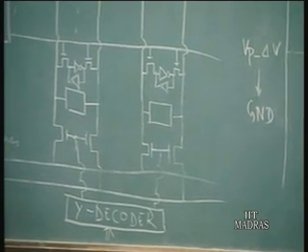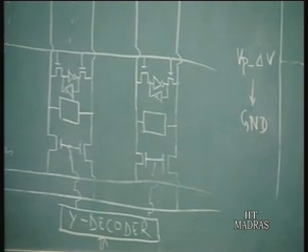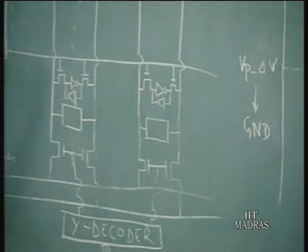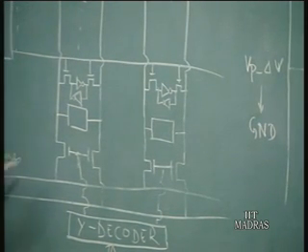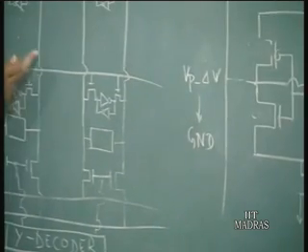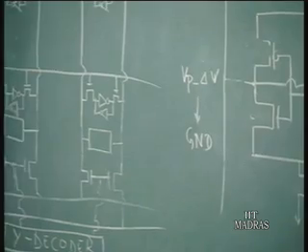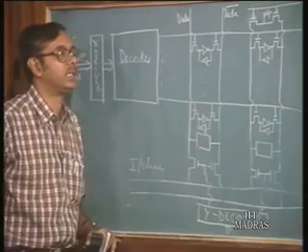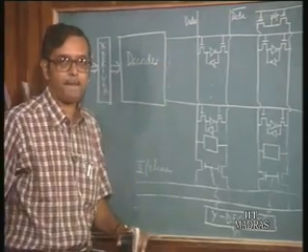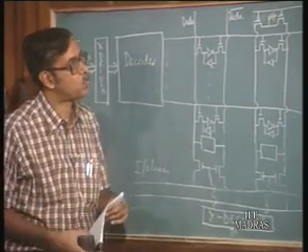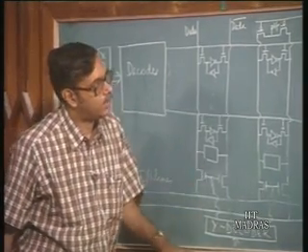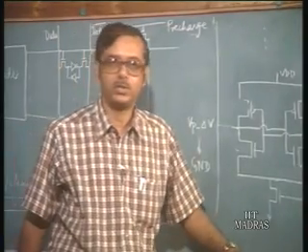So, for the writing mechanism, these IO lines can be used to write information into the cells by forcing voltages on these data lines. If one line is made to go high and the other line is made to go low, then you can write into a particular cell. So this is how a CMOS memory cell is going to work.